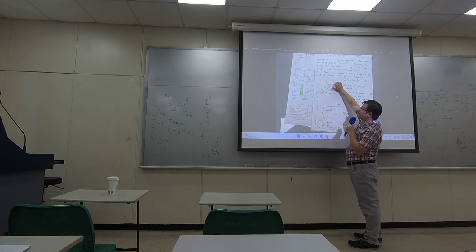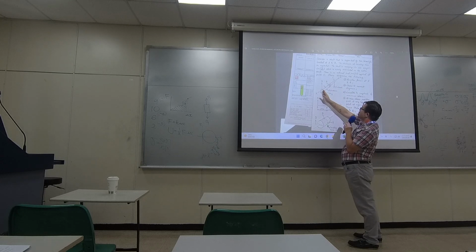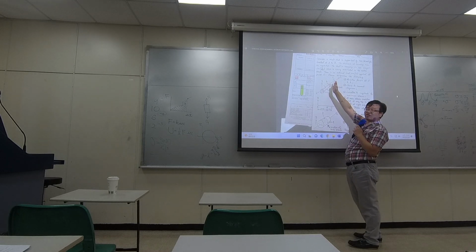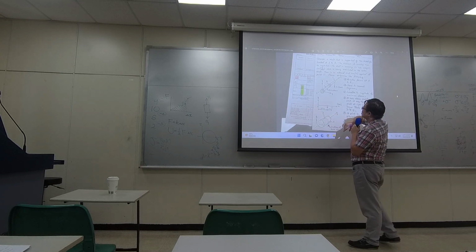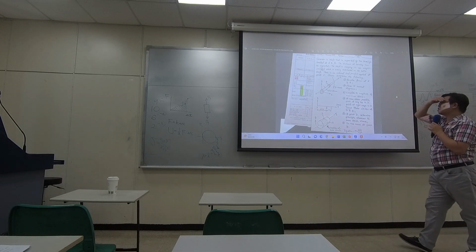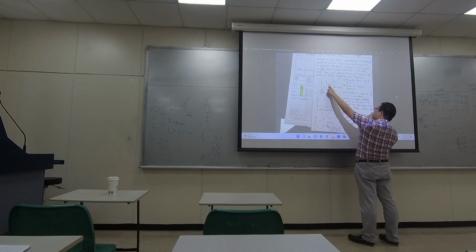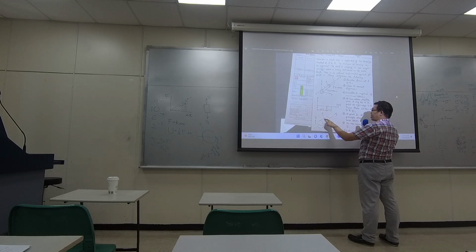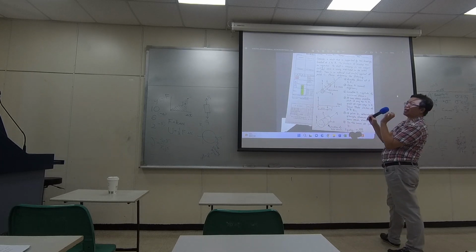This force is bending the shaft, and its own weight is bending the shaft. The reaction forces are bending the shaft. There's no torsion. So if I study this position, where I have the largest bending moment, and pick the top point, as you can see, it's being bent this way.